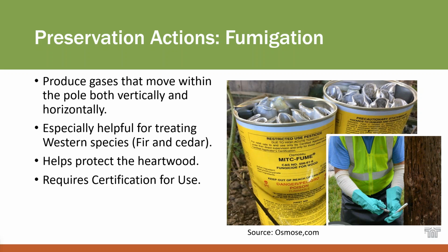With the treatment, the more hazardous the material, the better it is for protecting the timber, but also the harder it is to use. A lot of times you have environmental restrictions. For this one, it does require a certification for use. You have to be trained in how to handle this material properly and have a certification to show that you're able to do it safely. But it is definitely an option that's out there. I know some bridge crews that have taken the training and use this on a regular basis to help extend the life of the members. Basically you're drilling a hole into the interior of the member, and then you're applying this material into the inside of it, where it can protect that heartwood.